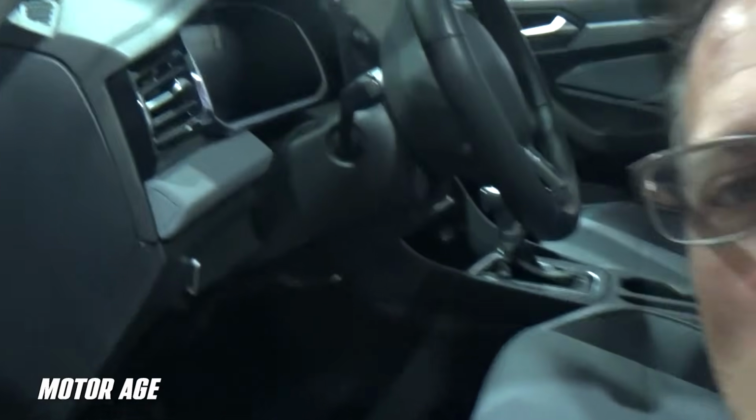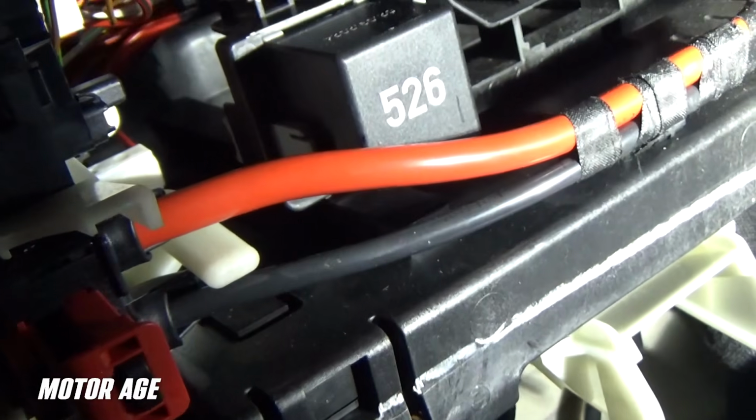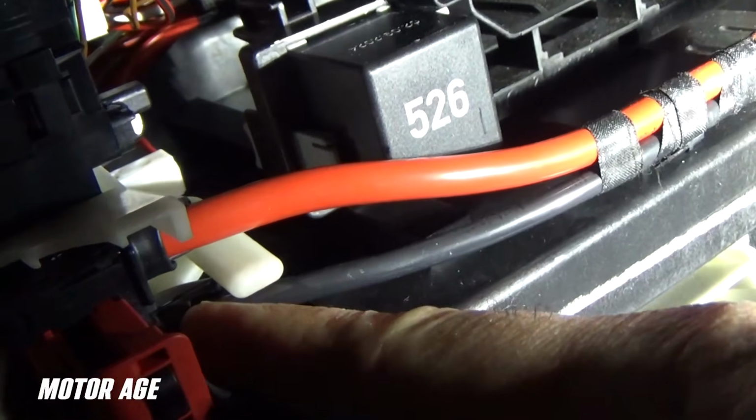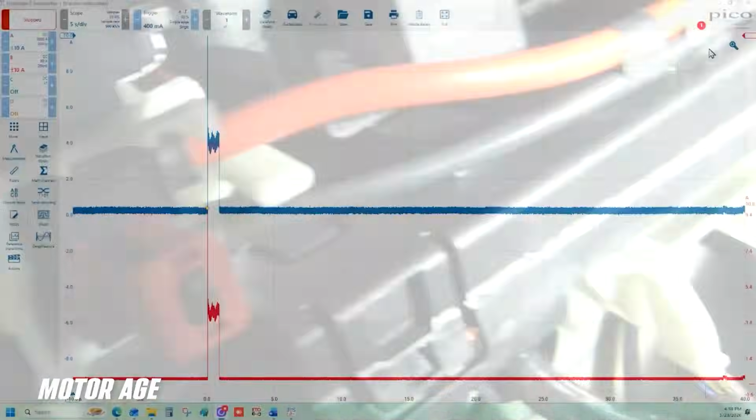So rather than troubleshooting the whole vehicle, trying to find this parasitic drain intermittently, we strategized, we leveraged the tools to eliminate 4/5 of the vehicle. And now we're only on this circuit. So let's take a look. I apologize, we're crawling under the dash here. This black wire right here leads to this fuse box. Now we just simply have to eliminate fuses. And that's a process of referencing service information and seeing which circuits are supplied current via this black wire.